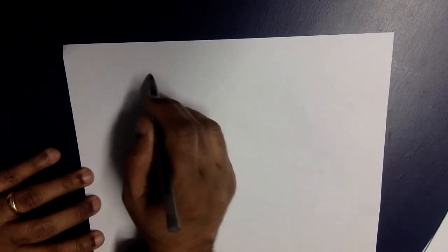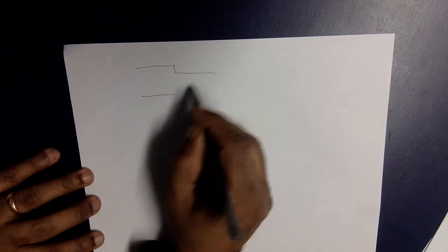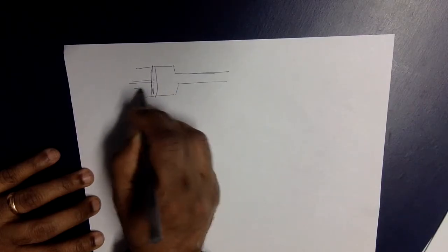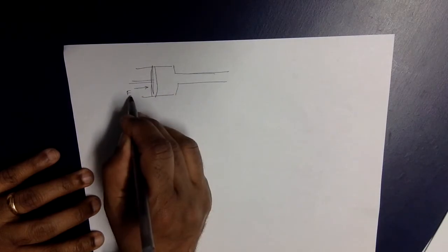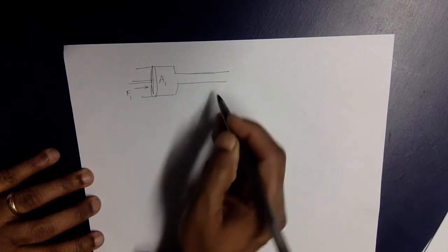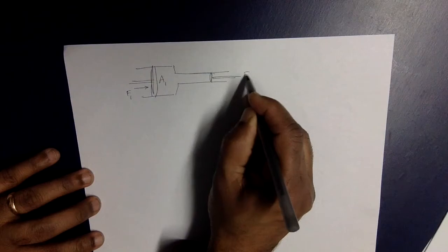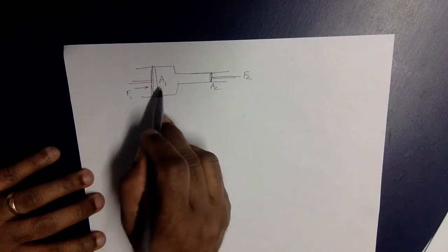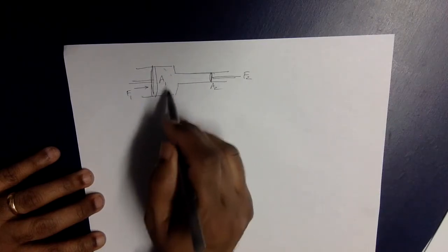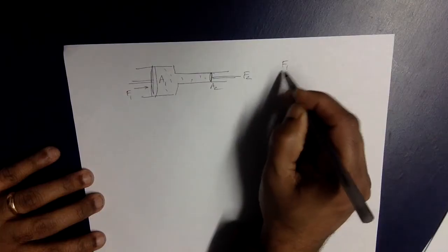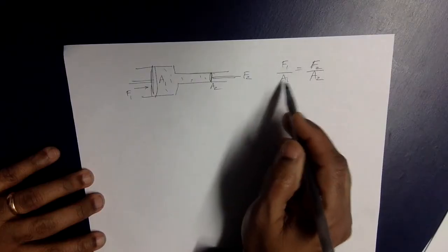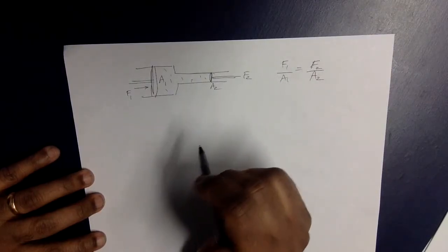Pascal's principle is, we learned it through the piston thing. So when there's a force F1 here and the area is A1, and there is the force F2 here and the area is A2, according to Pascal's principle, pressure is transmitted throughout the fluid. So that means the pressure everywhere is going to be the same. Therefore, F1 over A1 is F2 over A2. So if you know at least three of these things, you can find the fourth one.